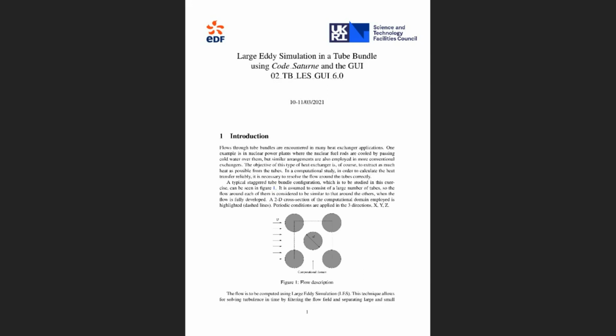The objective of this tutorial is for you to set up the whole case on the local or virtual machine. That's explained in the tutorial. And then when you're ready, copy the files across to ARCHER2, and then use a submission script to submit a job on ARCHER2. I mix up Archer and ARCHER2, but it should be ARCHER2 all the time.